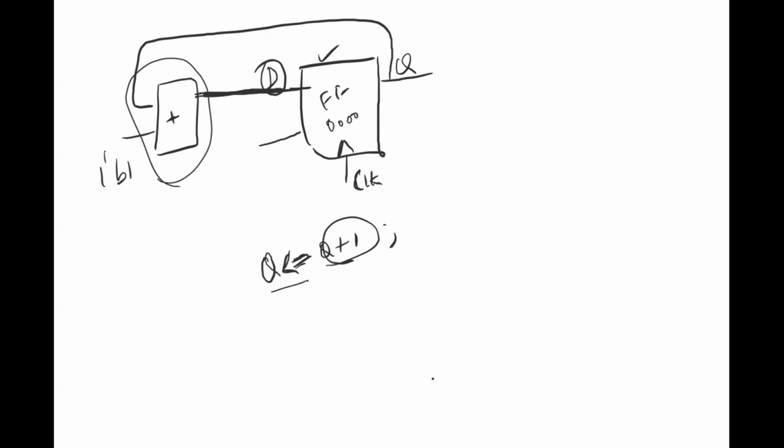Yes, not in the beginning, but once your always block starts, you can always say that if there is a positive edge of clock, if your reset is high, then Q is equal to 0, else you have Q is equal to Q plus 1, something like this. So whenever you hit reset, you'll obviously go into the 0th state, and you keep on doing that every time. I mean, because you also have a stop signal, you want to incorporate that stop signal somewhere inside this.